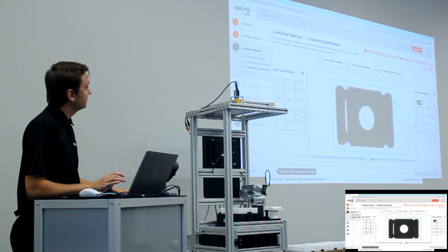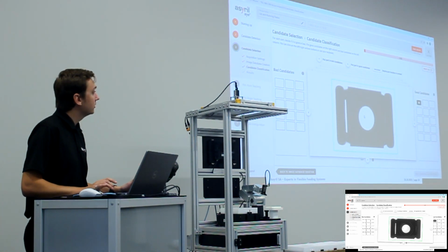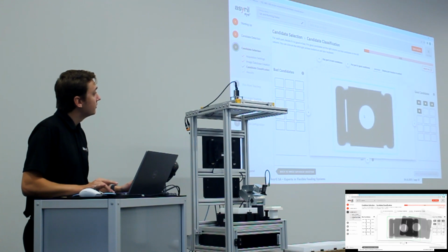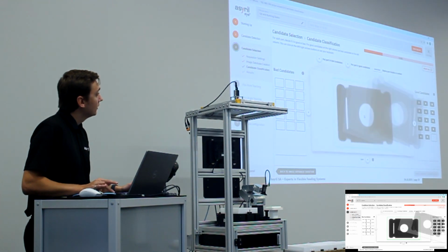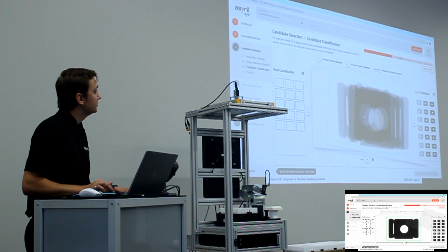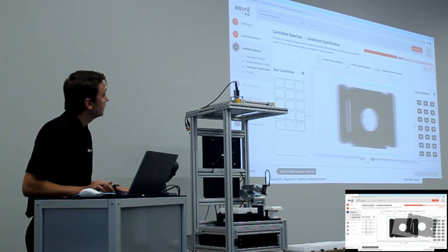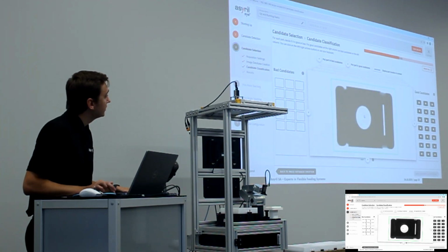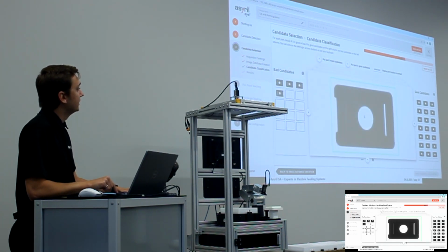That was a good part. So the first 28 parts that we took pictures of were good parts, so I'm just going to move them all over into the good side. This is typically how I like to train my I+ recipes, as it's easier and quicker to just move through all the parts at once. So then 27 and 28, now these are bad parts. So we're going to move them all into the bad candidates.